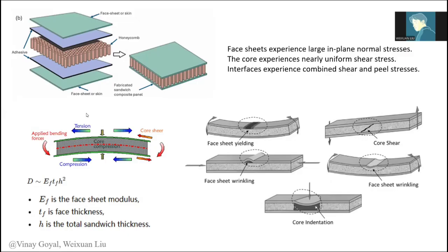In a modeling sense, the modeling approaches depend on the design questions. For example, if we just want to understand the sandwich structure in a global structure response, then we could use equivalent sandwich cell sections, directly input the shell behavior into the shell element. And therefore, we can capture the effective bending stiffness and the deformation of the plate or the panel itself.